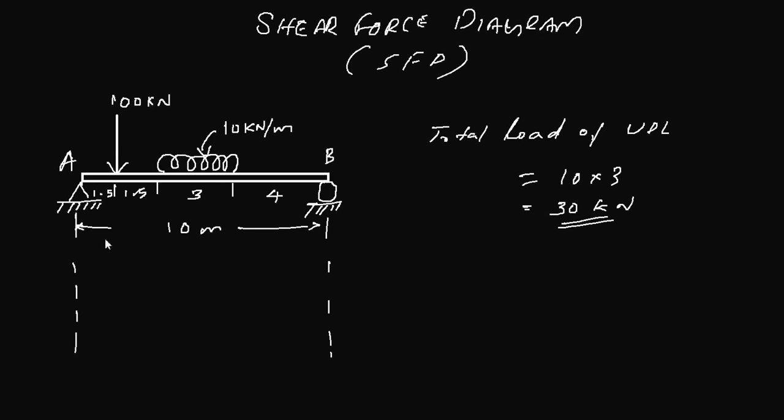So you can convert this force system into another one, into an equivalent one like this, where you have your beam, and what you do is converting your UDL into a point load. So you have one point load here and you have another point load here.